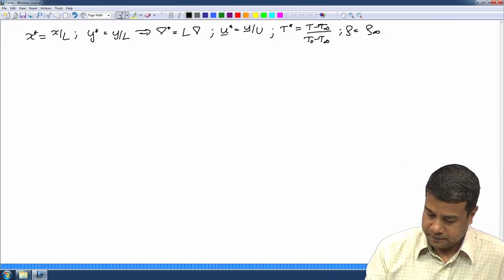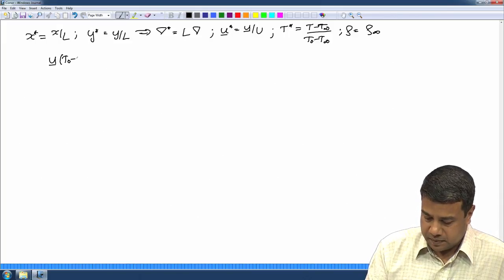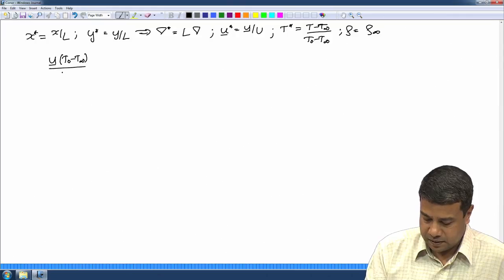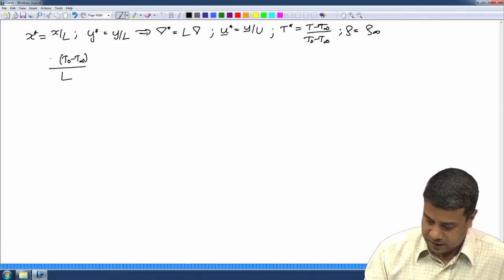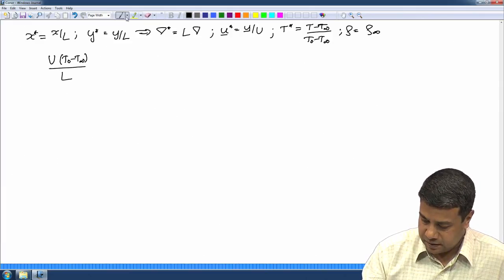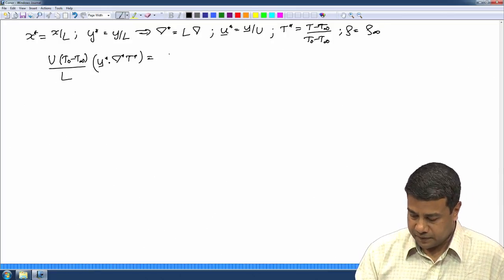Now, I will get u, the velocity scale, into T naught minus T infinity by L, into u star dot grad star T star, is equal to alpha times T naught minus T infinity by L square.